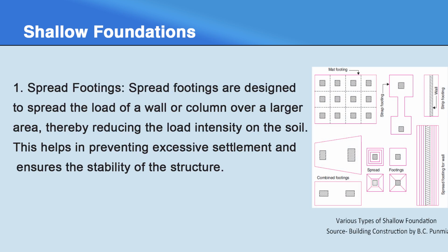So, first is spread footings. Spread footings are designed to spread the load of a wall or column over a larger area, thereby reducing the load intensity on the soil. This helps in preventing excessive settlement and ensures the stability of the structure.